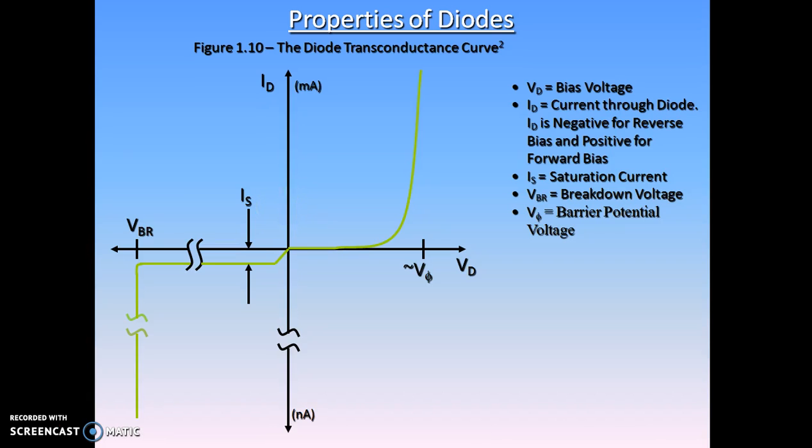the diode blocks current except for an extremely small leakage current and operates in the lower left quadrant. The diode continues to block current flow through it until the reverse voltage across the diode becomes greater than its breakdown voltage.